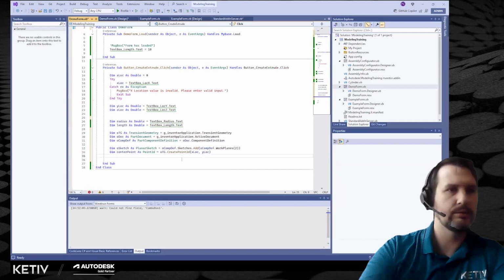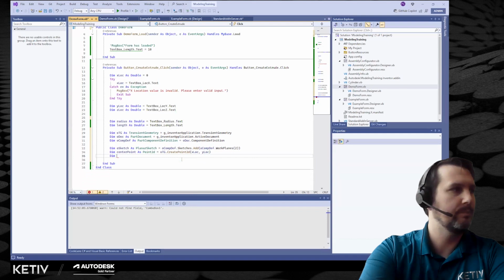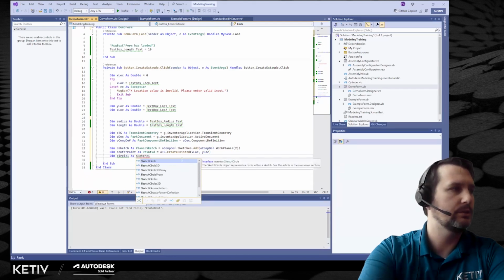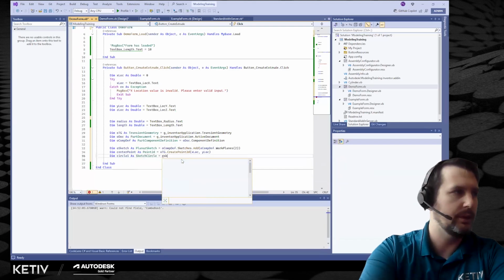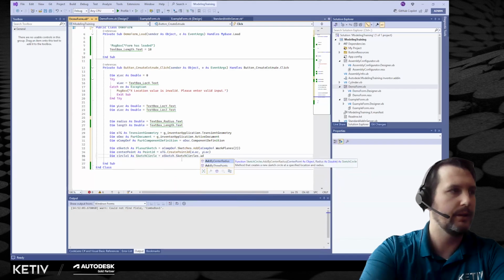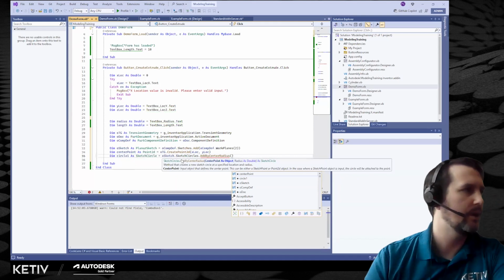Now we're going to make a circle. So we'll just name it, I don't know, circle 1, just in case later we want to make other circles, as sketch circle equals, now we need to get that sketch object and get the sketch circles dot add by center radius. That's the one we want. We can do by 3 points, but we have everything set up to do by center radius.